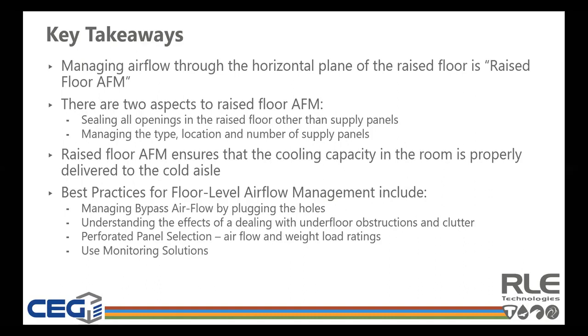We talked about raised floor airflow management as the phrase for managing airflow through the horizontal plane of the raised floor. And the two key aspects to raised floor airflow management: sealing only openings in the raised floor other than the supply panels, and then, for the second one, managing the type, the location, and the number of the supply panels.